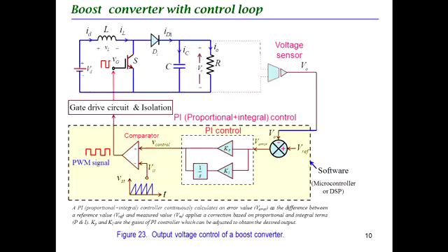So this is a conventional approach, if you are controlling the voltage across the capacitor in order to extract energy from the PV array or from the machine, which is the turbine-driven PM synchronous or induction machine. So that has produced the VD, the grid or the wind turbine has produced a VD, and energy from there goes to the capacitor after the boost converter. But the boost converter would normally be run like that with a PI controller to control the output voltage. Having said that, this is a very primitive approach.